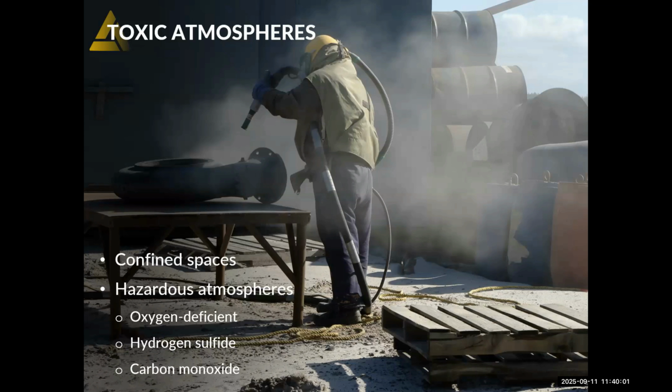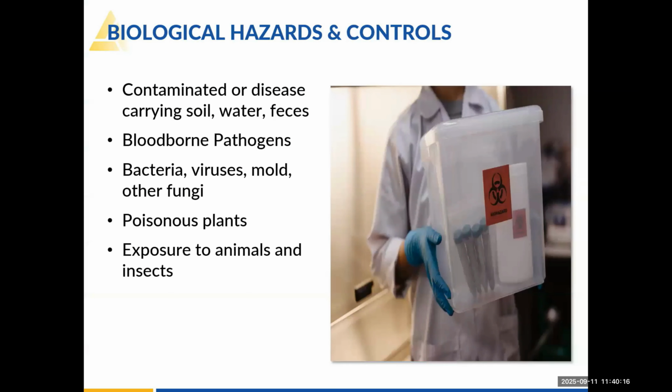You might be depleting your oxygen. You might be creating carbon monoxide. You might be creating an explosive environment, but you don't know that unless you do some kind of an air test or air sample to figure out what's in there. Next slide, please. And I think we have Chris up to talk to you about biological hazards.